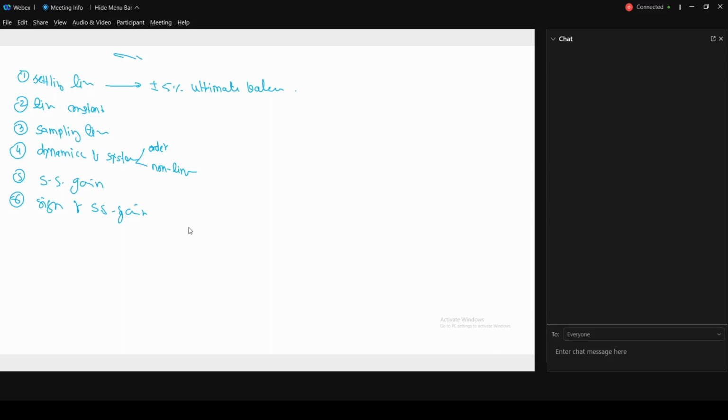That is the time I will call the settling time. And for time constant, I know the thumb rule: it's the settling time divided by 5, and sampling time is the time constant divided by 50, in general, in practice. Okay, so I get this information once I have given the step change.